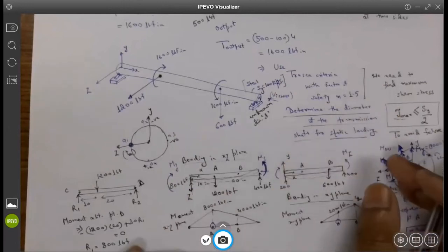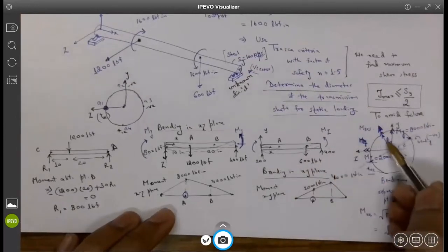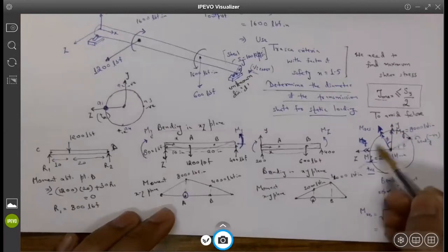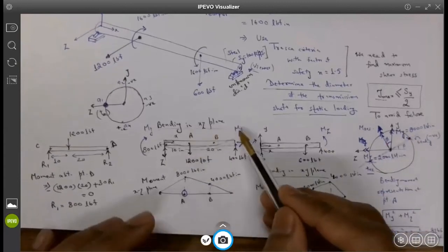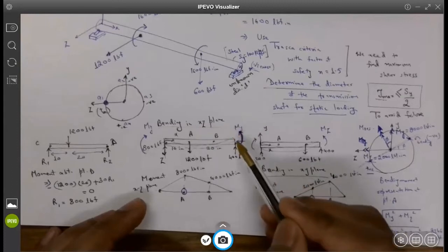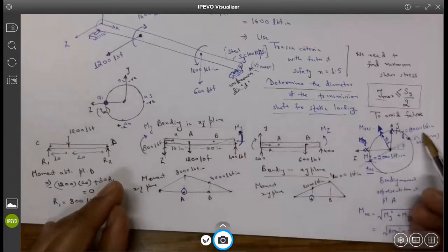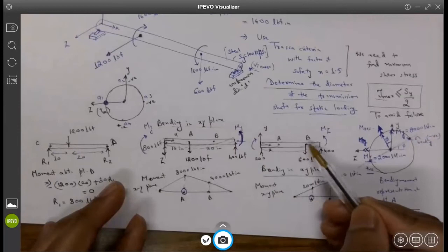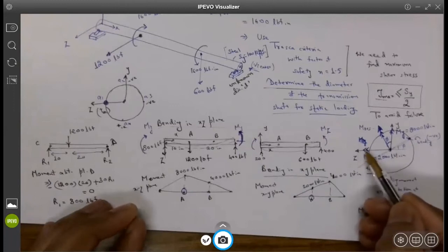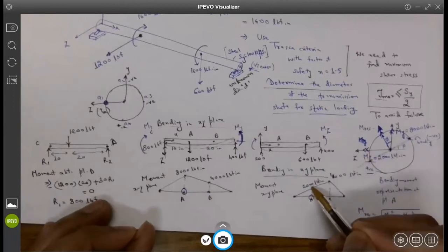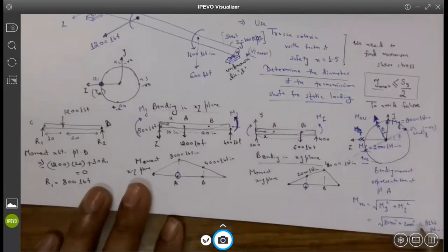Yes. The same thing we have done for the XY plane. As I said, the resultant bending moment vector would be pointing in this direction because it is a resultant of My and Mz. Now M subscript Y is basically the bending moment for the XZ plane. That is what you have to always remember. This bending moment acts in the Y direction, but it bends the beam in the XZ plane. It's positive Y direction, 8,000 pound force inch corresponding to point A. And similarly, MZ is basically bending in the XY plane, pointing in the Z direction. At point A, it has got 2000 pound force inch. And the resultant of these two is basically pointed this direction, which you have told me, 8246.